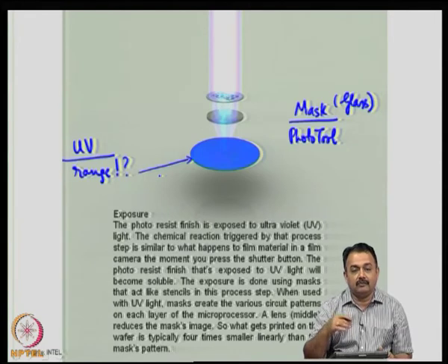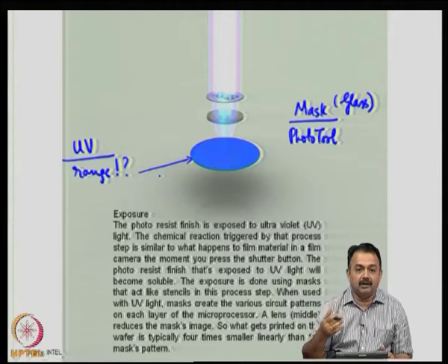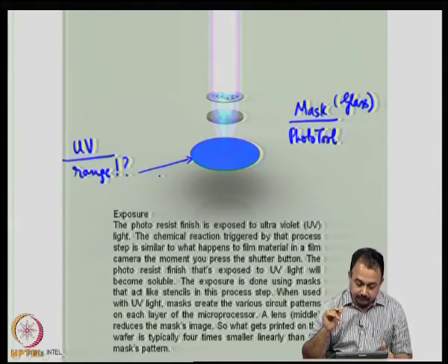So, initially you have to look at the material, look at the compatibility of the frequency or the wavelength of the UV light that you are using, and make some trial and error findings. And if you are satisfied with the minimum error that you are getting from this set of experiments, then you can proceed with this. Or in some cases, the photoresist manufacturer will suggest the thickness and the UV intensity to be specifically used for the semiconductor fab applications.